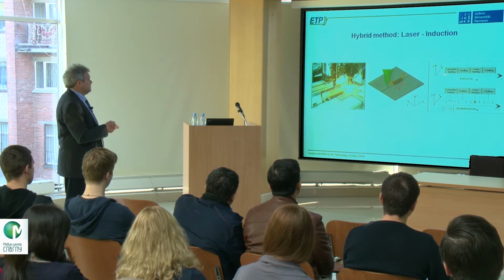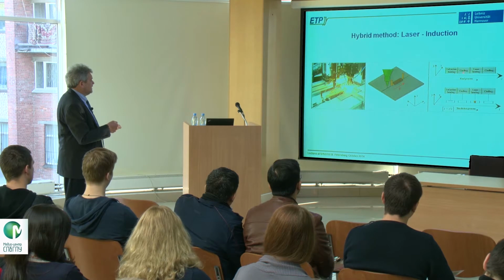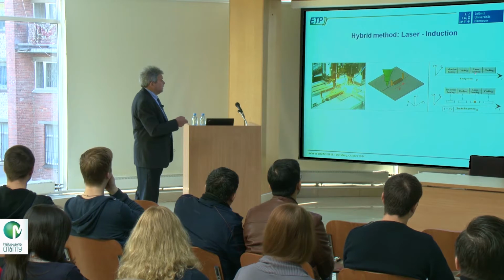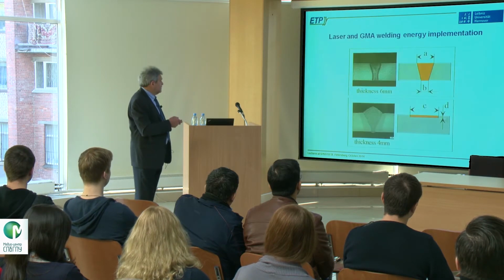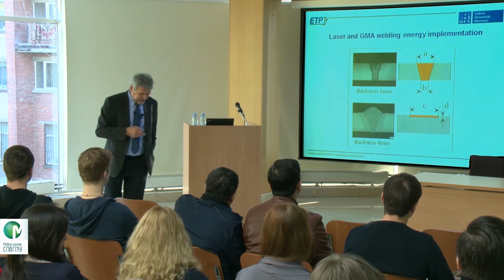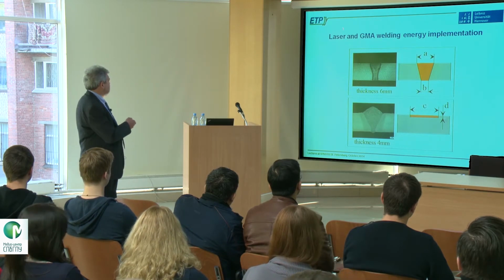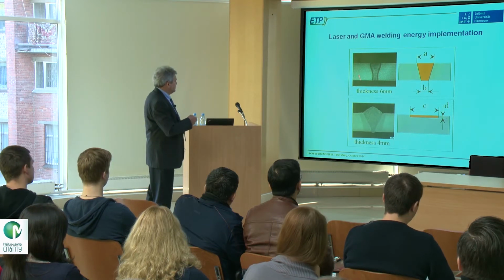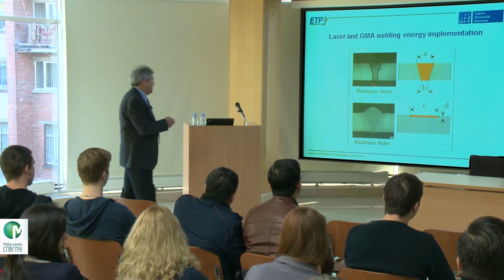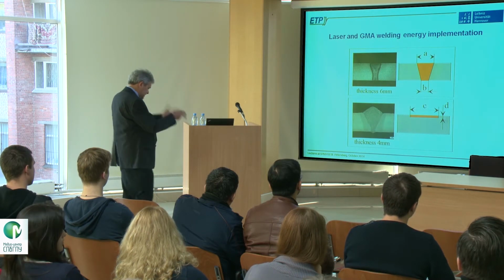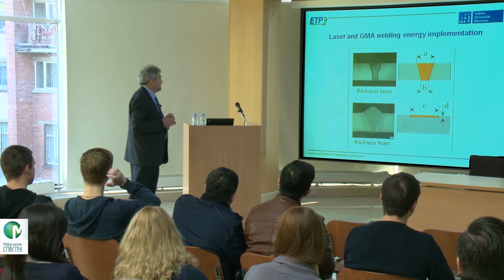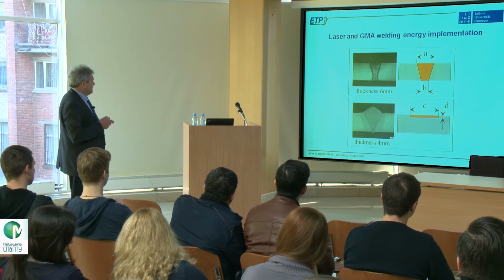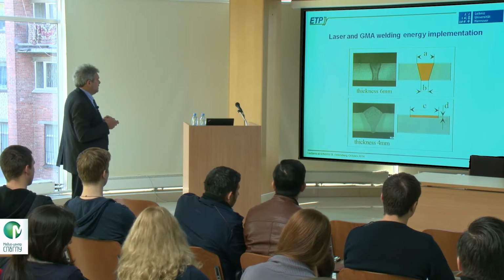Now we have realized a simulation model that takes into account induction heating, which we know of course very well, but also takes into account the laser heating. So we had to choose, for the implementation of the laser or also the arc heating inside the seam, the heat sources where the laser is generating the heat. Our laser colleagues, of course, they were laser experts. They had some experience with that, and they gave us their information and data.